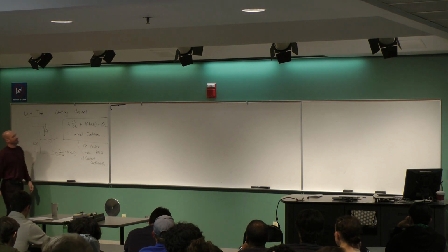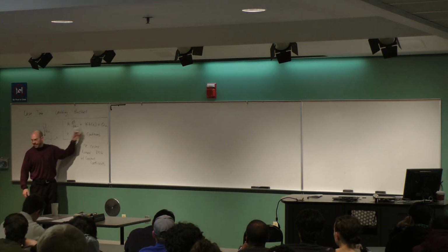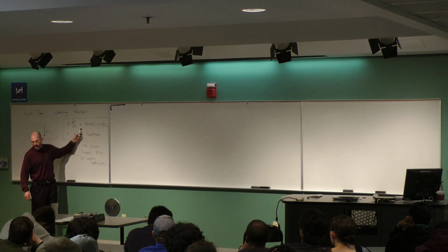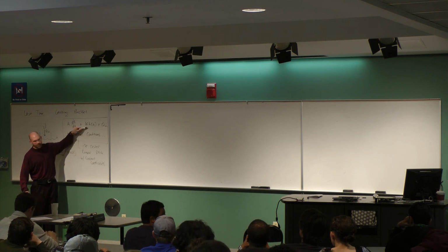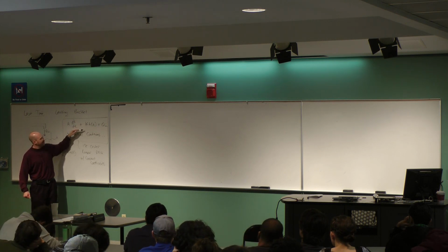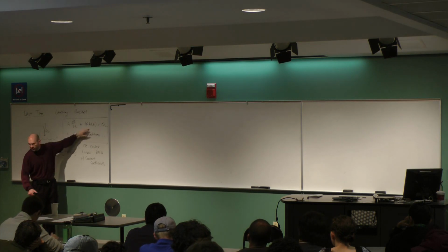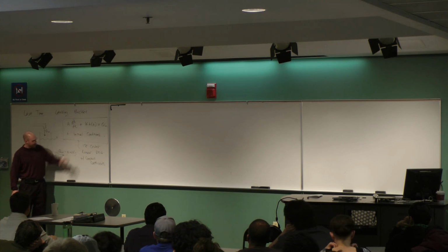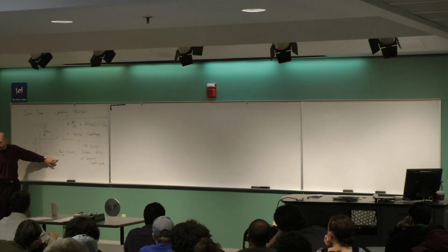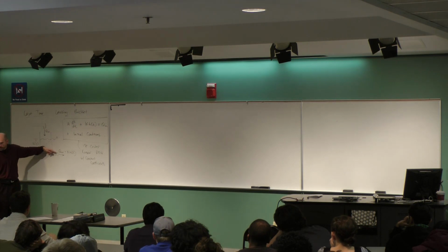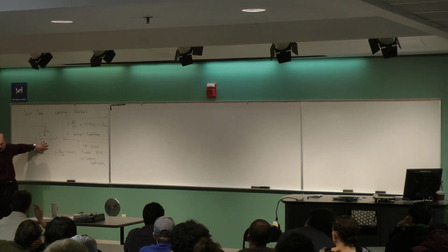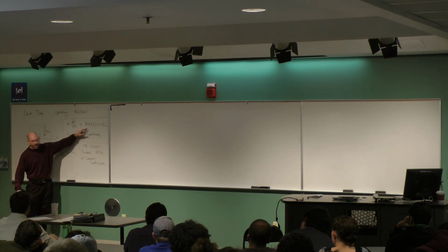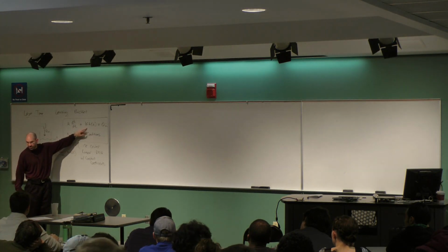Okay? In addition, these terms are just a linear combination. In other words, I got one term with a derivative. I'm adding it to another term with a function. I don't have a square root in here. I don't have a sinusoid. These a's and these k's: A is the cross-sectional area, all right? K, proportionality constant here, depends on what kind of valve I've got. It depends on what kind of fluid is in here. Is it molasses or is it water, that kind of thing. So that means the A and the K are just parameters that are constants.